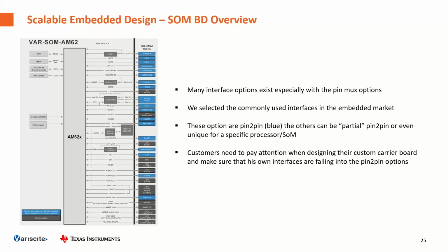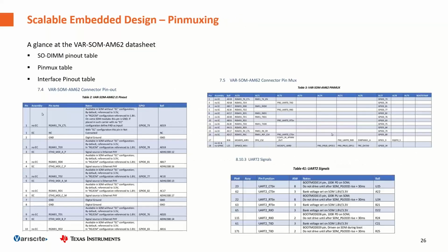Pinmuxing capability of the SoC, but let's try to understand what the Pinmuxing is. So basically, every pad of the SoC can be programmed to have a specific function. In the hardware there is a kind of multiplexer that allows you to choose the right function for that pad. This must also match your ordering info. So for example, if you order a SOM with the Ethernet controller, so the PHY on board, parts of the pins may have different allocation.